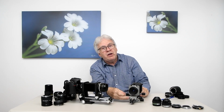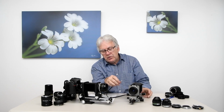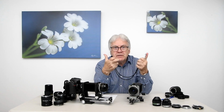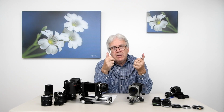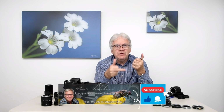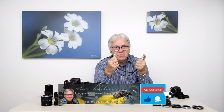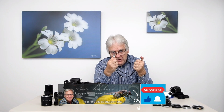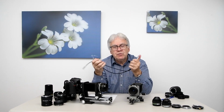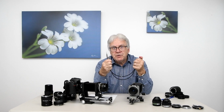Of course, to simplify this function, Olympus and Nikon and other companies have created the mechanism that opens and closes the diaphragm so that it can be connected to a double cable release. The double cable release has this function. When you first press the shutter halfway, the first cable release closes down the diaphragm. And when you press down the rest of the movement, the second cable releases the camera shutter. So it's a continuous movement. Close down the diaphragm, take the picture.